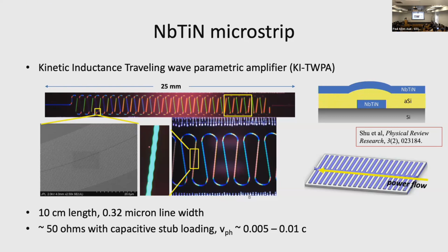It's a thin, or narrow, conductor to enhance the nonlinear effect. But then it has a series of stub sections periodically attached to it. One purpose of these sections is to decrease the characteristic impedance by adding some capacitance to this line.